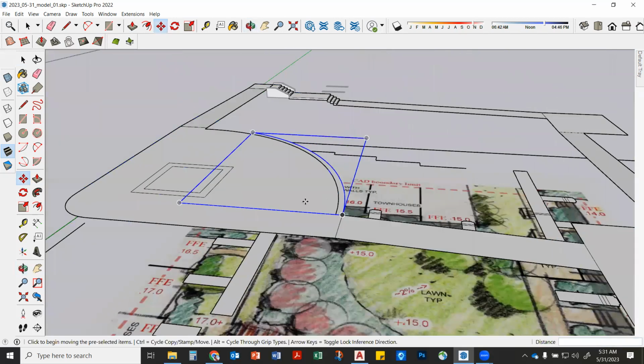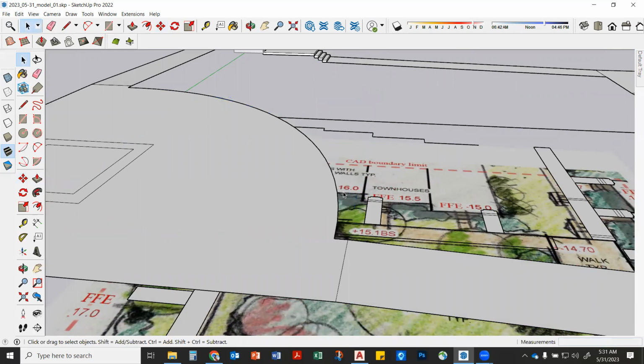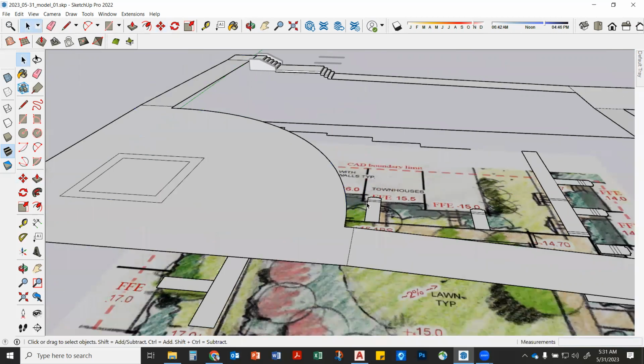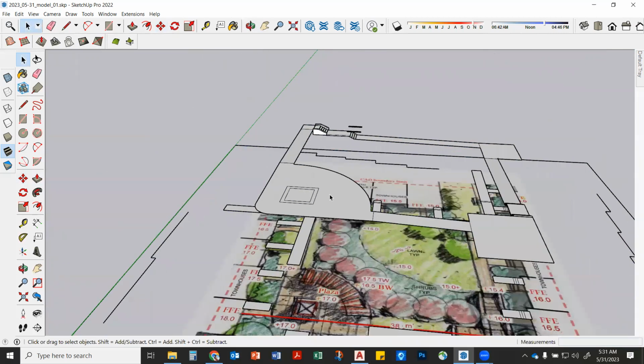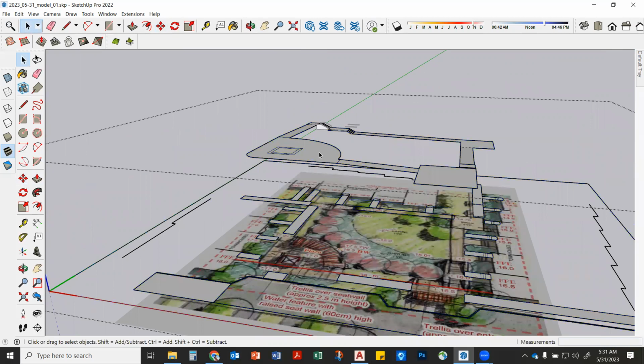Now, yours is probably not in the correct group, yeah? How do we get it in the correct group? Are all of these things grayed back? Make sure you have it in the correct group. You still have that one selected. Control X, which cuts it, right? Then double click inside the group with this plaza and all the line work we've been doing, so we're inside that group. And then what are we gonna do? Edit, paste in place, right? Edit, paste in place. Boom.